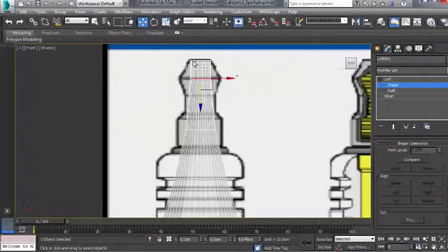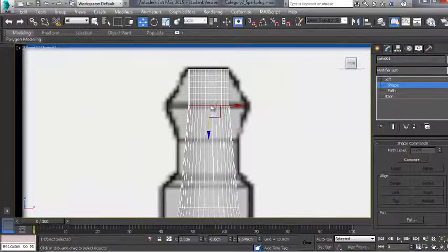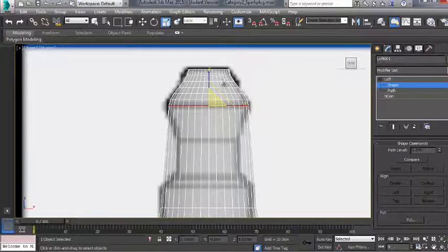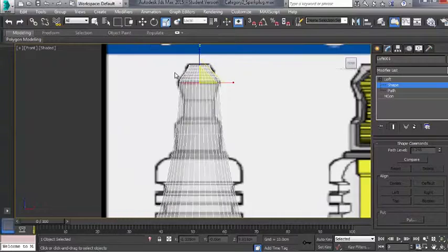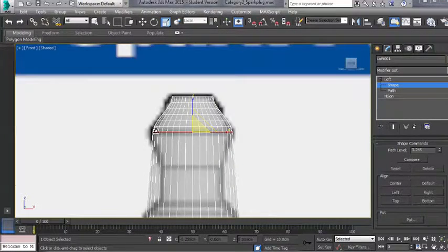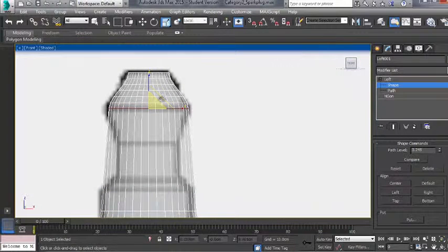So you can see there it's created a new one. So we can press R and select the uniform scale tool. If I scale that up, there we go. We have it scaled up and it's in line with that. There's a bit too much geometry going on here, like all the detail with all these edges in between those two edges, and I want to try and reduce that.